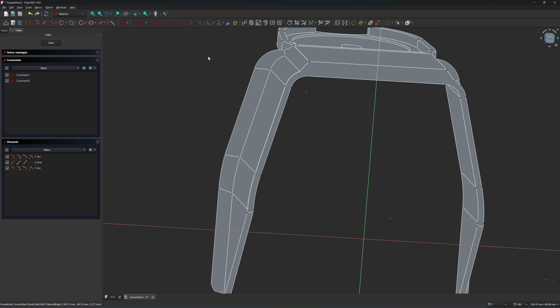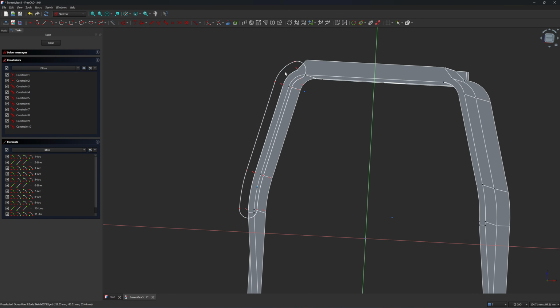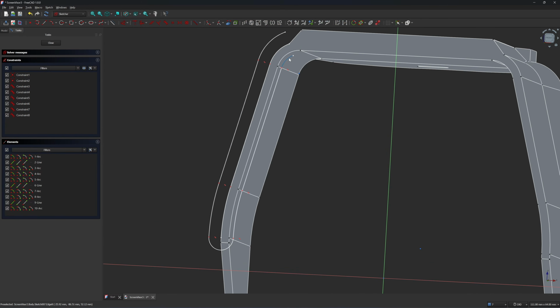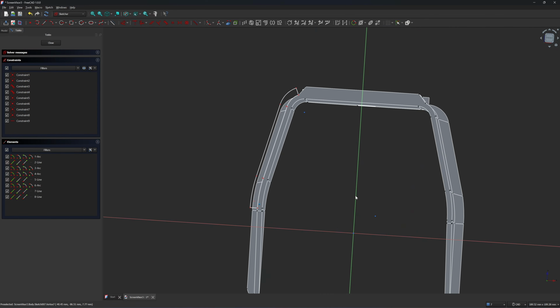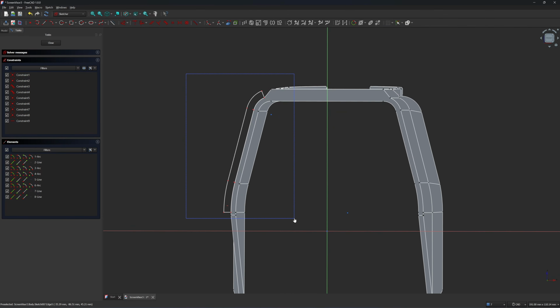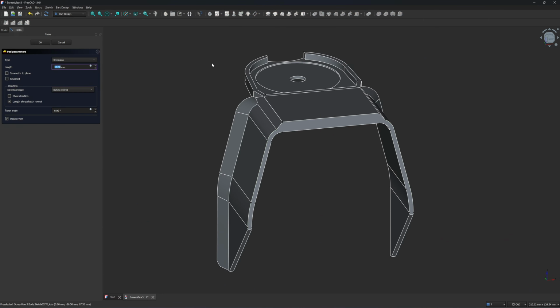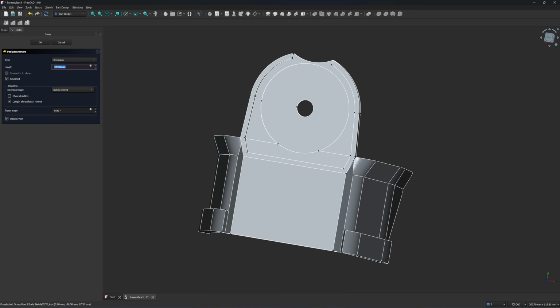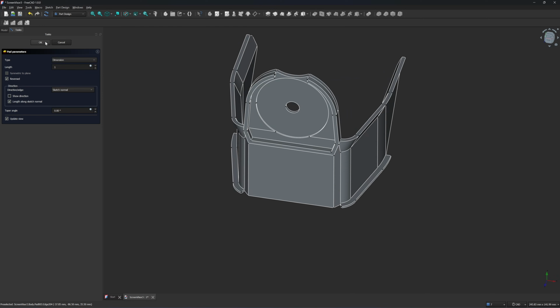Doesn't matter. Okay, I select all the lines, I'm going to offset this line to 3 millimeters, and then I'm going to delete the unused line. Then I'm going to connect to closable lines. I should have a closable line, right? And next I'm going to mirror this to the other side. Okay, let me close this. I'm going to extrude the sketch reverse 1 millimeter, so it doesn't have to be thick. About 1 millimeter is enough.